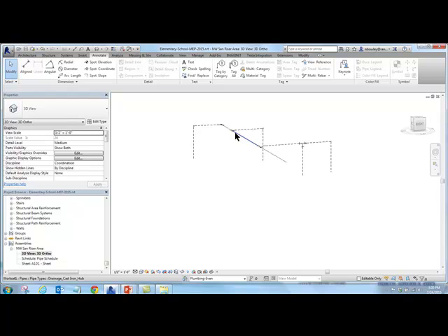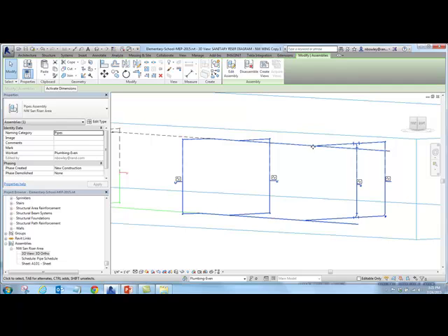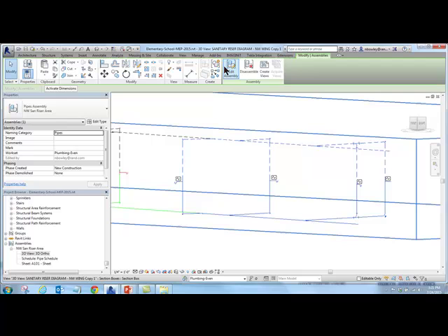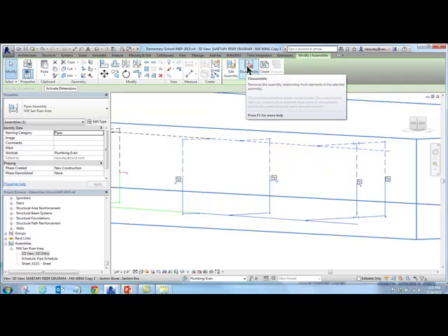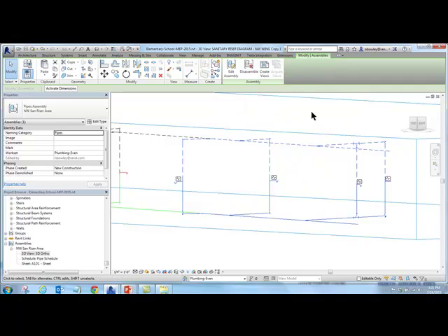You do want to be careful and let people know what it is. If you're still pretty early in the design phase and somebody clicks on the pipe, like, oh, it's a group and I got to explode it. Well, you're not really going to explode it, but you want to make sure that they don't, because that'll kill everything. If I click on that, it's all locked together. Ideally, if they were modifying those pipes, they would hit edit assembly. But what's probably going to happen is someone's not going to care and they'll hit disassemble, and then you lose all your stuff that you had set up. So just be conscious of that.